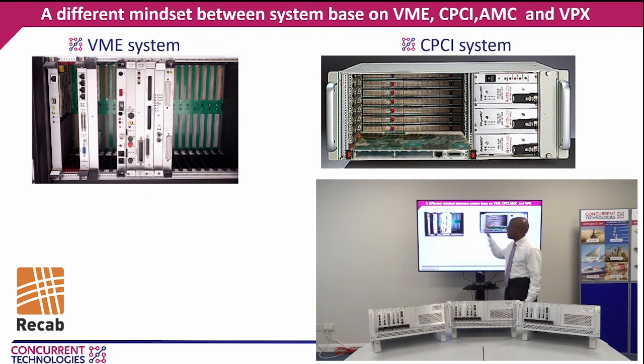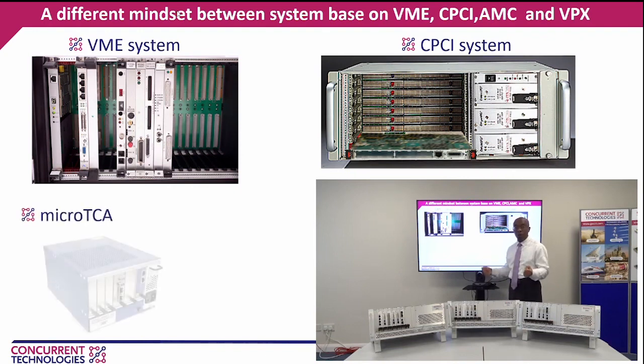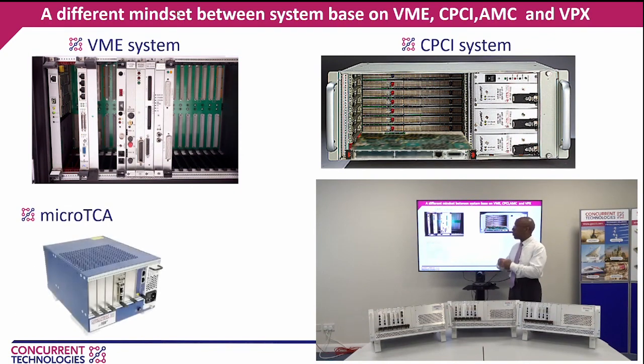Now, with these two legacy technologies, the data bus and address bus go to all the slots, and that's why it was very easy to use any board in any slot. The technology moved on, and to increase the bandwidth between slots, this has all been serialized. So you end up with something called serial fabric, where you have point-to-point communication. And this has also been used in backplane type technology.